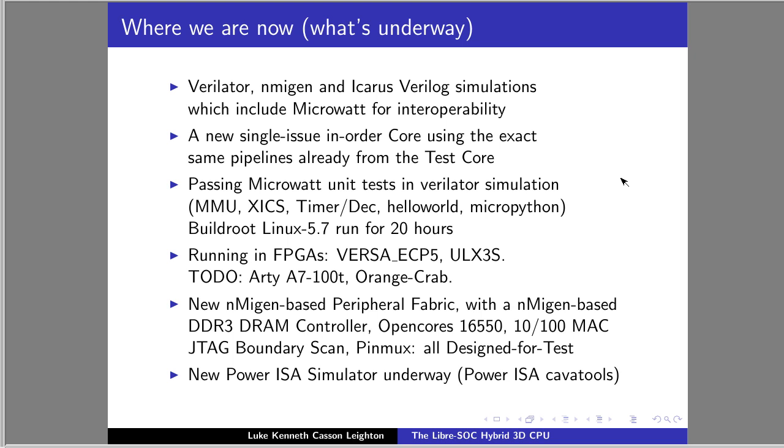Right? You don't need a PinMux, whereas with an ASIC, once you've put it into silicon, you've paid your $250,000 for 45 nanometer, or your $1 million for 28 nanometer, or your $16 million for your 7 nanometer masks. The last thing you want to do is to say, oh, by the way, if you want to use a UART instead of an I2C, you're going to have to buy another chip. Absolutely the last thing you want your customers to do.